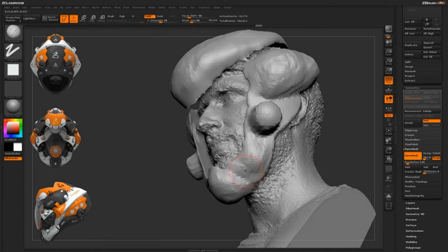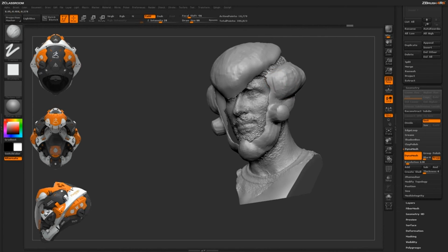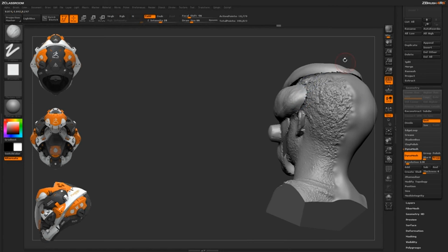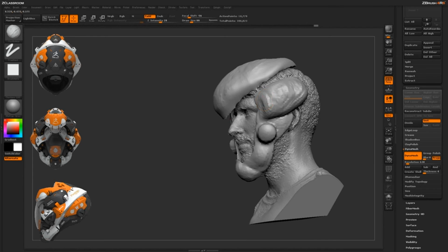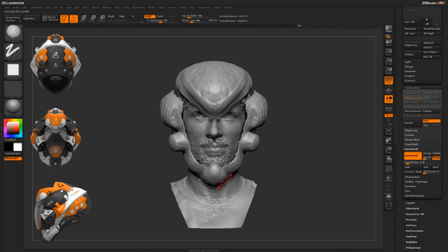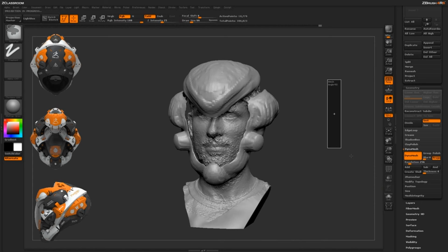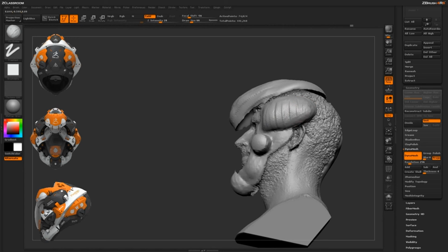So another little thing there, if you start sculpting on really fine stuff inside of ZBrush and you start losing some of that form, just turn on your back face mask, and then you're going to get a little more control over the model there. So you just continue building up these shapes to establish those helmet details. Just clay brushes through here, and then if you need more resolution in certain areas, you can just redynamesh. You can up the resolution slider over here, so say something like 256, and redynamesh, and you can start getting more and more of those forms fleshed out.